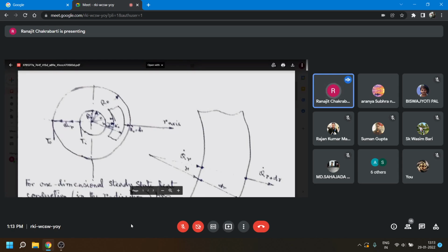You start from the three-dimensional general equation for heat transfer. Then from there you go to the two-dimensional conduction equation, the general equation. Then from that you come to the one-dimensional equation, removing the other two dimensions. Then from that you come to the spherical coordinate form, and there is an energy generation part that you also make zero. So finally you come to the equation, and from that equation using the boundary conditions you can come to the solution, right? That is one approach.